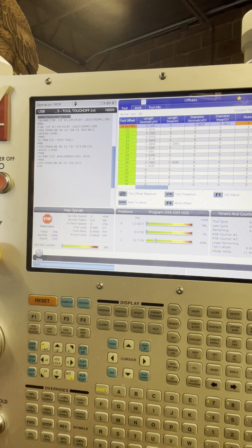I don't have any compensation for a bigger tool, like a big shell mill. So I'm just looking at length. I'm not looking at diameter too. It gets a little complicated the way that mechanism works. So it gets you close enough that you can move it 2 times and then set that number in there.